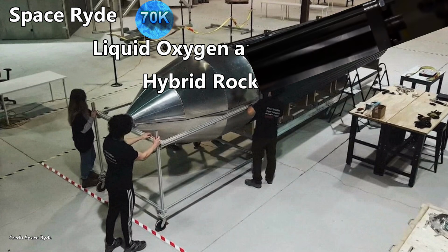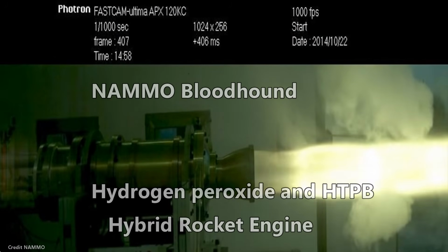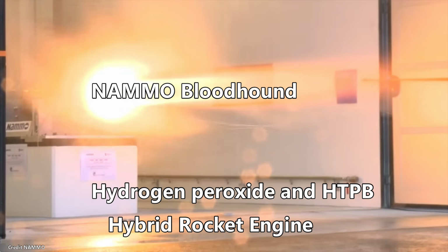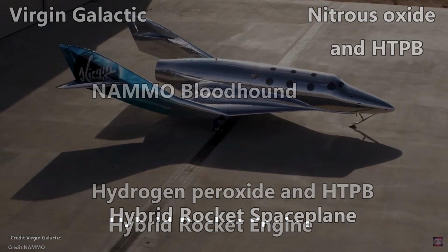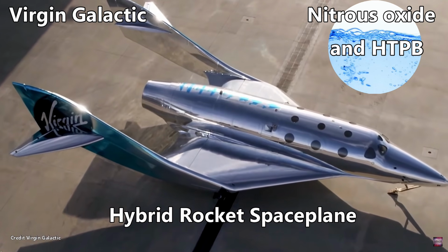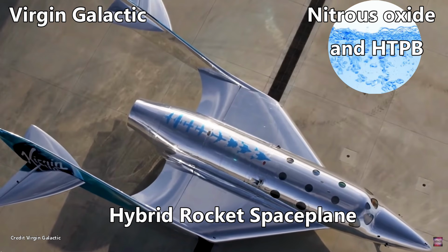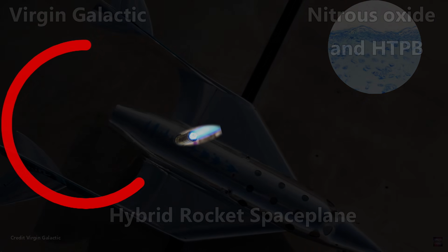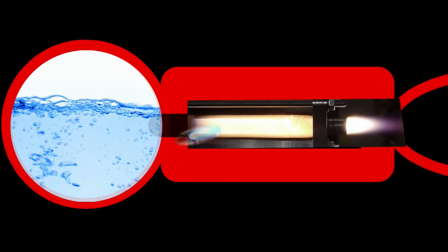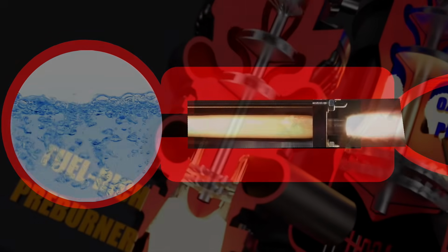Pumps are used for big rockets, but smaller ones can be pressure fed. Hydrogen peroxide can be sent over a catalyst bed and can pressurize itself. Nitrous oxide, when it's being pumped, will actually break down into oxygen and help self-pressurize the tank. Once the oxidizer is in with the fuel, an igniter is fired. It can be another pyrotechnic or a small gas-fed blowtorch. Either way, the ignition temperature is exceeded. Now let's look at liquid bipropellant engines.